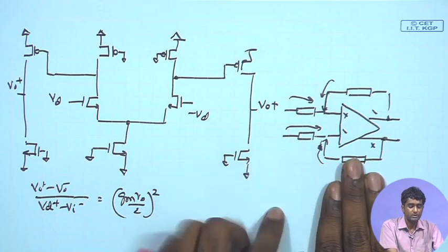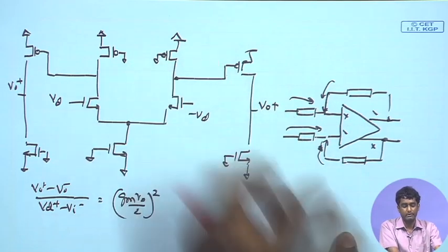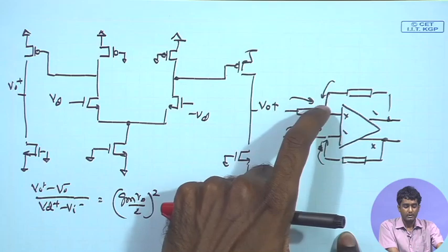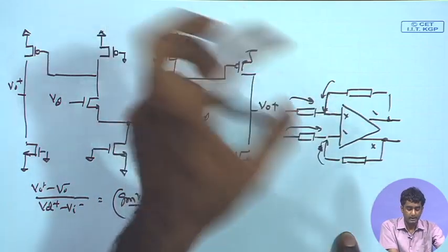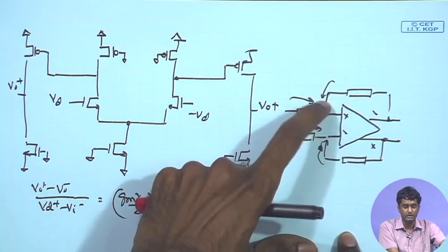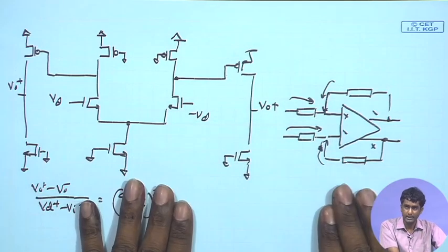Likewise, in the differential operation, we are relying on these feedback elements to give us a well defined gain with the help of these passive elements, in this case capacitors. But in this case, apart from getting the gain, we also need to make sure that we are having sufficient or appropriate DC bias at the input point. So, both these factors again need to be analyzed here.